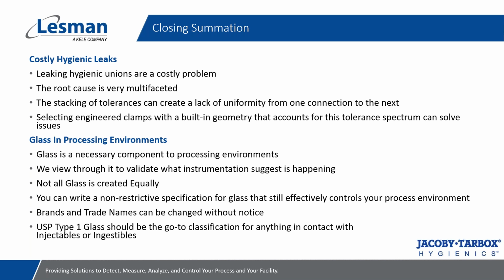when there's foaming in the vessel that might be giving a false level. We go to that window to view the process. We want to validate, yes, it's foaming, or yes, the tank's been clean and it's empty. Certainly having a window to view through into your process, I believe, should be considered a critical component, but not all glass is created equally.